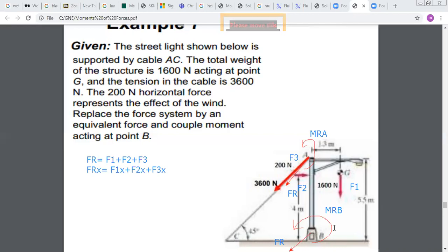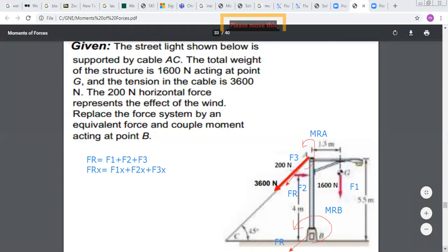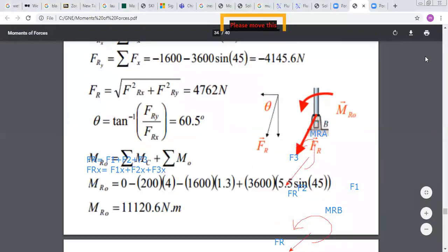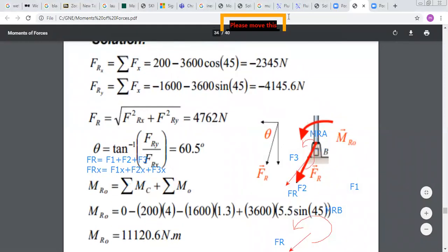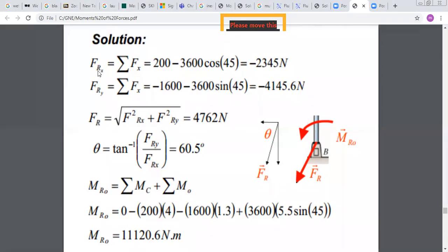And how do we find the force and the couple in the equation? From the equations, of course. To find the resultant force, you say first, what is the definition of resultant force? The definition of resultant force is the summation of forces. And since here you have a 2D system, to find your resultant force, you can first add the x component of all forces, and you find Frx. Add the y component of all forces, you get Fry, or here you have a typing error, it's y.